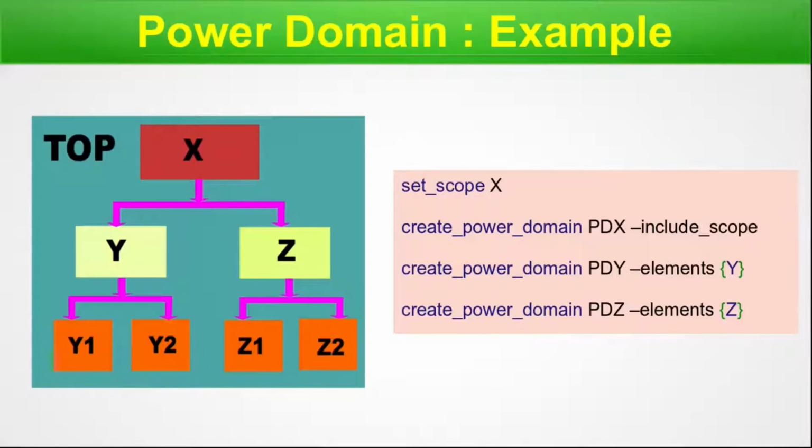We have gone through two examples to understand how we do that. And this slide is the extended concept of the previous one. So we are done with this slide. Let's move on. Power ports and power net. Now guys, these are very important things. When you design a chip with the HDL, it will not operate if it does not have the power ports and the power net. So this is the important part of the UPF that we are going to learn.